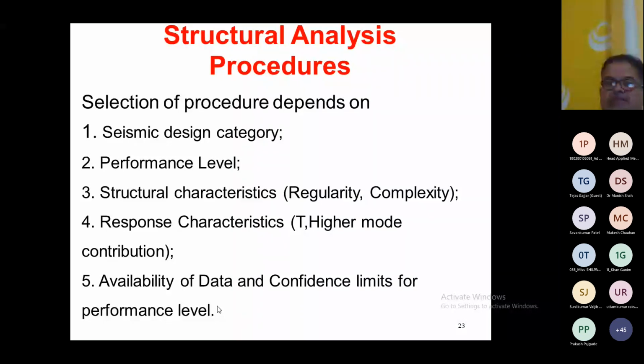Performance level means we have different performance levels: life safety, immediate occupancy, collapse prevention, many different types of performance we are defining, and on that basis also we select these methods. Structural characteristics: whether your structure is regular or complex, right? Suppose your structure is irregular, in that case definitely dynamic analysis is preferred.